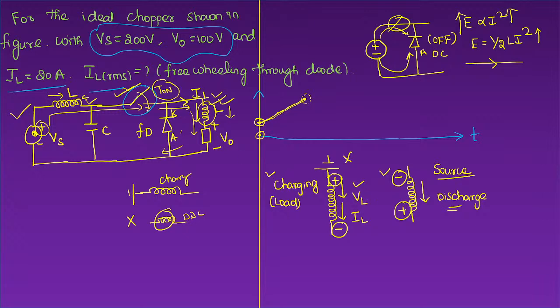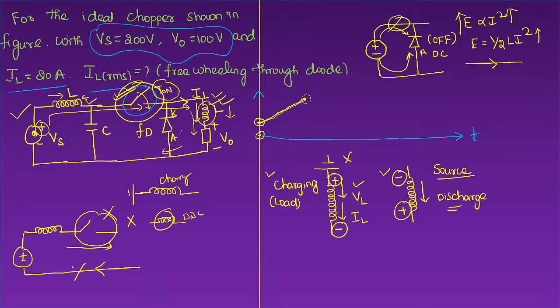It will discharge in this loop itself. See there, you have disconnected this switch. Once this switch is disconnected, what is the point of having the return path? There is one inductor, but the switch is disconnected, and you have the DC supply. Of course, you have one more path to return, but one path is blocked. So when the forward path is blocked, the return path will not work. So what will happen? The energy stored across the inductor will come here.